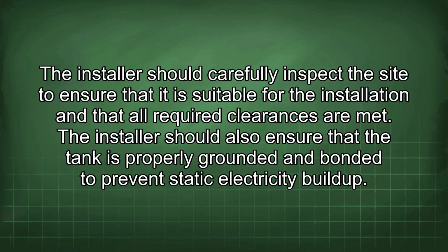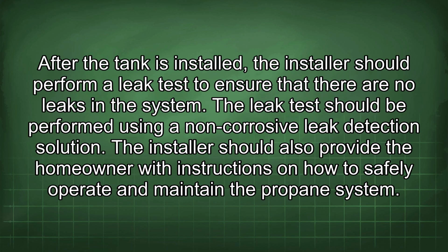The installer should carefully inspect the site to ensure that it is suitable for the installation and that all required clearances are met. The installer should also ensure that the tank is properly grounded and bonded to prevent static electricity buildup. After the tank is installed, the installer should perform a leak test to ensure that there are no leaks in the system. The leak test should be performed using a non-corrosive leak detection solution. The installer should also provide the homeowner with instructions on how to safely operate and maintain the propane system.